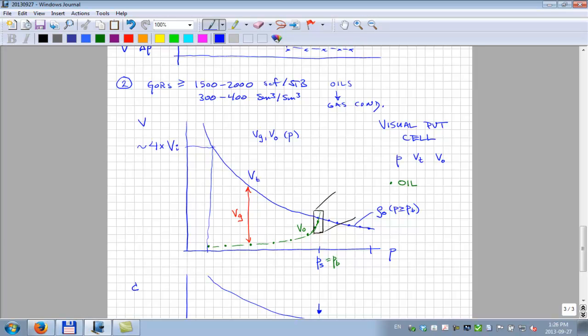If you have an MDT type sample, it's at reservoir pressure and temperature. So you can pressurize it to 1,000 bar. Make sure it's single phase. Likewise, a bottom hole, cased hole, traditional bottom hole sample, you can also make sure it's single phase, charge it directly into the PVT cell. So for the bottom hole samples, you can make sure that the sample container is single phase. You then push the fluid into the PVT cell.